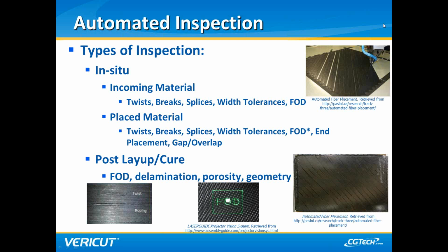And then post layup and cure, again, the big thing here is that you're not going to typically be able to do much with your part if you find errors at this point, because you're already fully covered. If you find that there's FOD a quarter of the way through the part, there's not much you're going to do with it other than report that it's there and determine whether or not it's going to be an issue for that specific part.